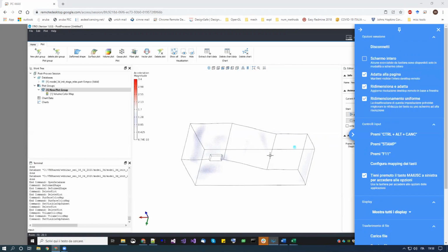Yes, I told it in the beginning of this webinar. When I was doing the 2D examples, I was following some of the examples I found online, and they always talked about using an increased thickness in the 2D case. But actually, I was running this 3D example, and I started with defining different materials. Of course, I cannot use an increased thickness because this is 3D, so I was using an increased stiffness. But actually, I've seen that nothing changed. So I prefer to keep just the standard stiffness of the soil material. It was not changing anything.